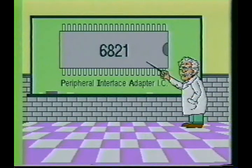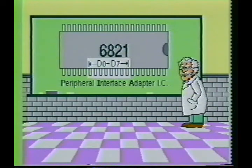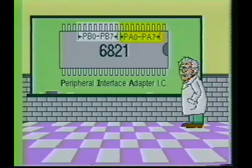The 6821 is a peripheral interface adapter, or PIA for short. It is constructed using NMOS technology. The microprocessor can read data from or write data to the 6821 through the data bus lines D0 through D7. The 6821 also has two peripheral ports. Port A uses pins PA0 through PA7, and Port B uses pins PB0 through PB7.